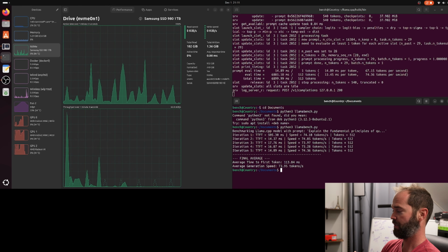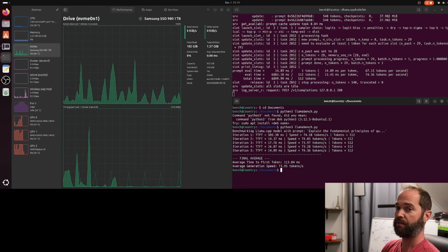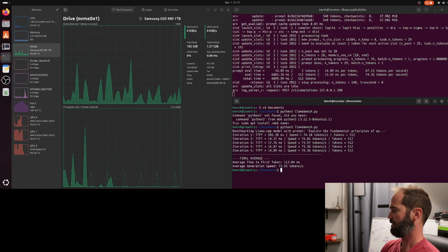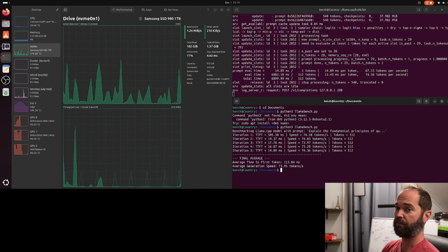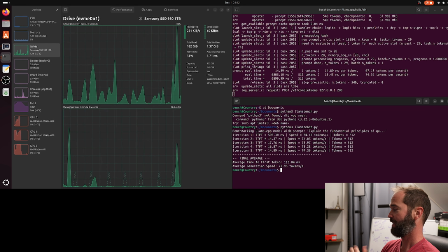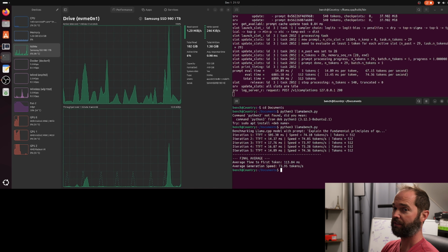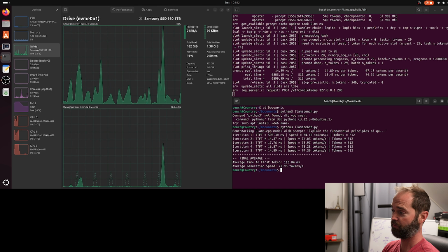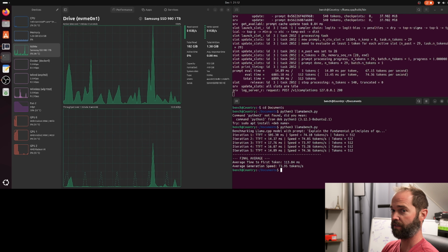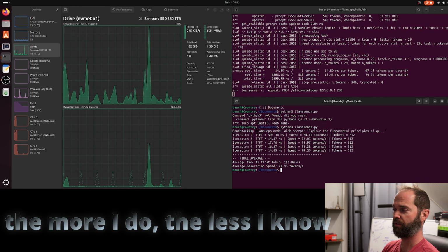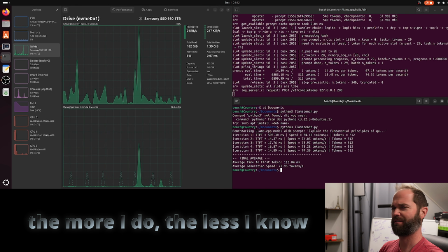And again, this motherboard splits GPU lanes 1 and 2, 8x8 to the CPU, and then the third 16 width slot is only 4 lanes, and it goes to the chipset. And it's really interesting. I'm not surprised that it did better, I'm surprised that it did that much better. I thought that third card would really choke out, being that it was going through the chipset. Still learning about this. So many intricacies.